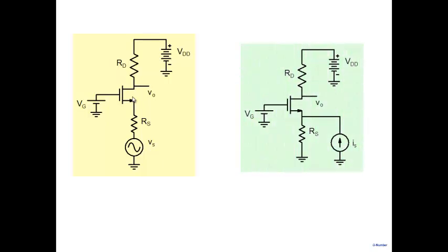But we also saw that if instead of voltage as an input, you give current as an input, which means that the input is a current source, meaning that the resistance RS is large, then what happens is, because the common gate amplifier input resistance is small, this entire current, instead of opting for RS, will actually flow into the common gate, into the source. And once it flows into the source, this AC sinusoidal current will flow out through the drain. There's no other path.